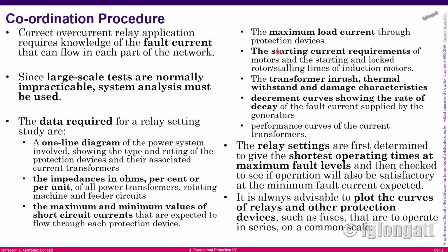You must know those values, because your overcurrent protection must not trip in that case. But there are many other examples, for instance the inrush current of transformers. When you are energizing a transformer, there is another big current with a very short duration. You don't want the overcurrent protection tripping for that, because again, it's a normal overcurrent in your system.